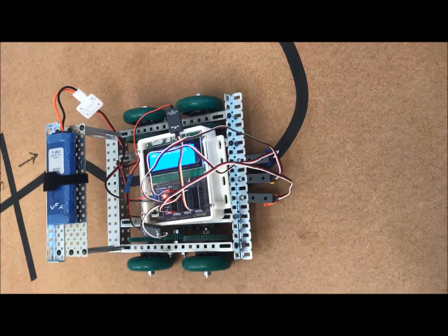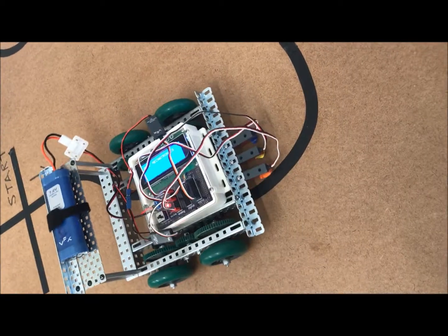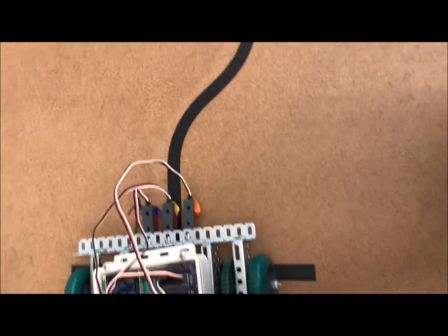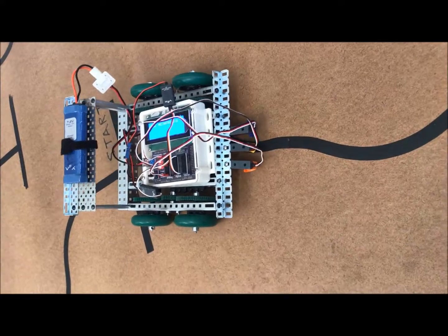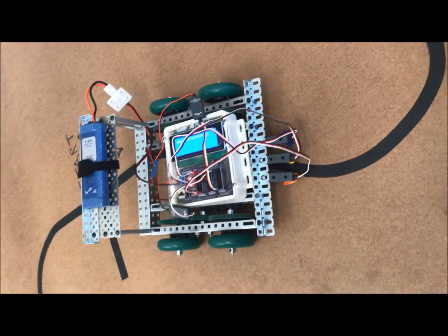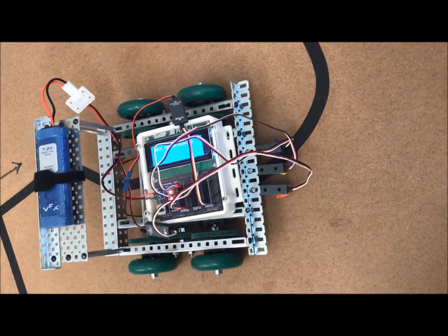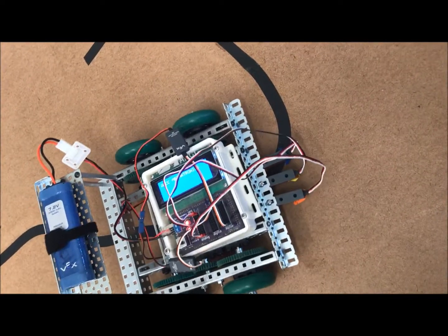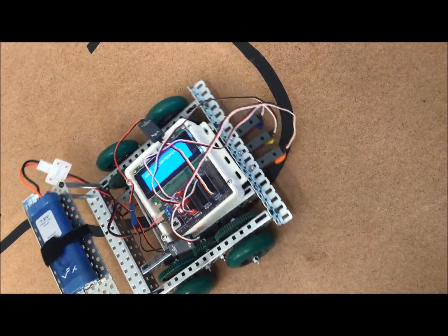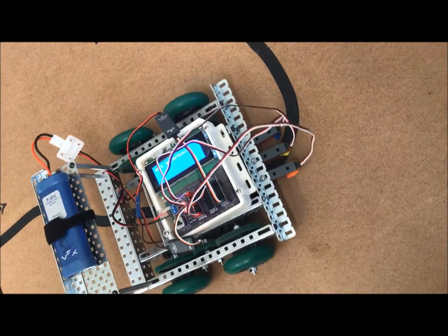Another issue that I had was the spacing of the line trackers on the front of the robot. My initial thought was that they were supposed to be about a medium length, maybe 1 notch apart from each other. But from certain turns, as you'll probably be seeing in the footage in the background, I thought that the line trackers needed to be spaced further apart. And when I did that, based on the code that I had at the time, certain turns would work and then some would not. So I ended up in this situation where I was stuck. I could either turn sharp or I can turn wide. I wasn't able to make every single turn possible.